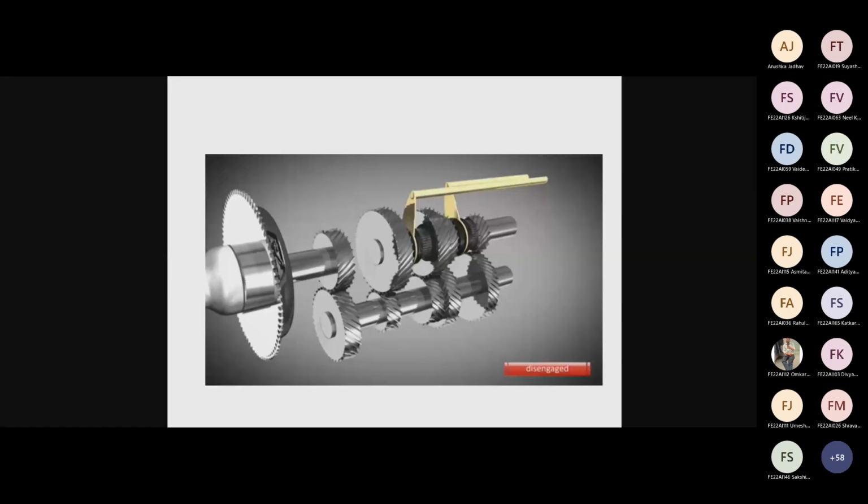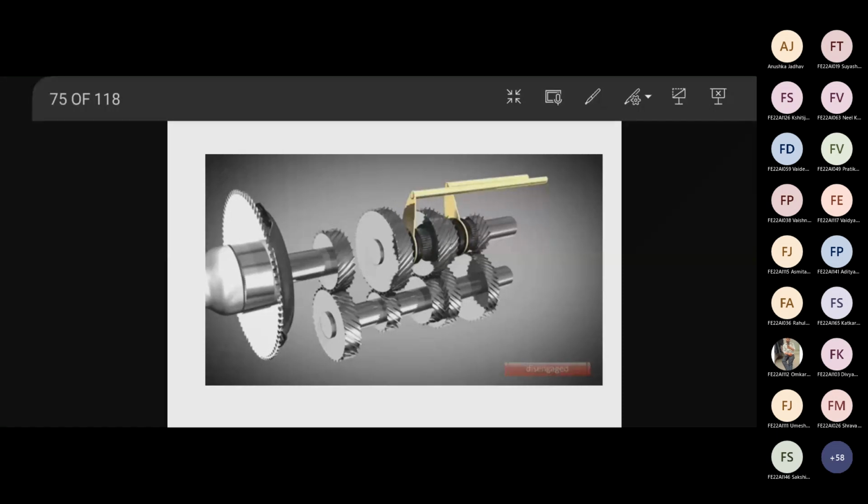So here this is the main shaft, right? Flywheel. From this shaft, power is transferred to this gear, and all these gears are freely rotating on the shaft. In between these are the dog clutches, and these are the levers connected to your gear lever to shift the gear, right? When we are moving this dog clutch, your gear starts rotating, right?